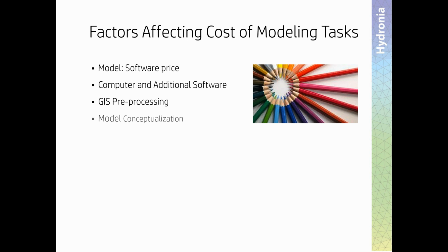Then you need specific tasks to make. GIS pre-processing of the data: you need to process the data to put it in the format that is most appropriate. You need to conceptualize your hydraulic situation. How are you going to conceptualize the site, the inflow and outflow conditions? Where are you starting and where are you ending the mesh? Are you going to develop the mesh refined in some areas and less refined in other areas? There are many things involved in the model conceptualization. Then comes the model setup itself, how you set up the model, and this usually involves the use of a graphical user interface.